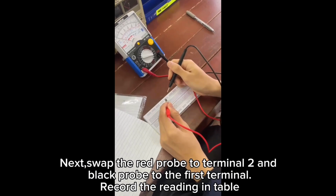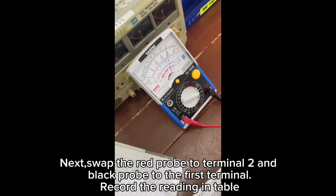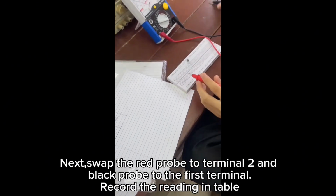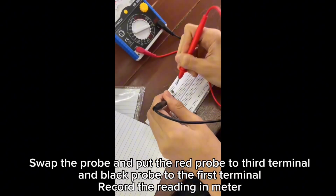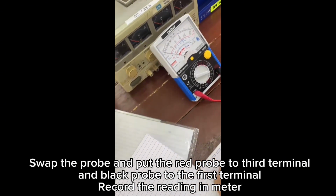Next, swap the red probe to terminal 2 and black probe to the first terminal. Record the reading in the table. Swap the probe and put the red probe to the third terminal and black probe to the first terminal and record the reading in the table.